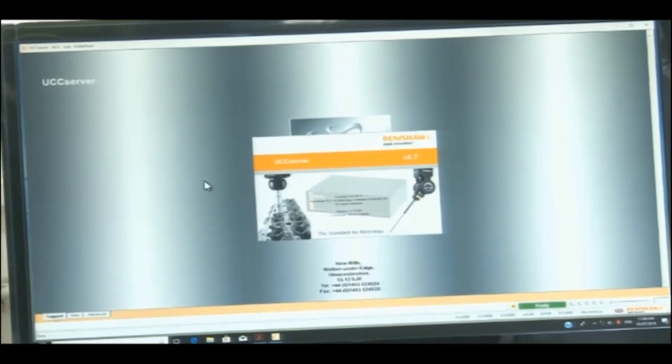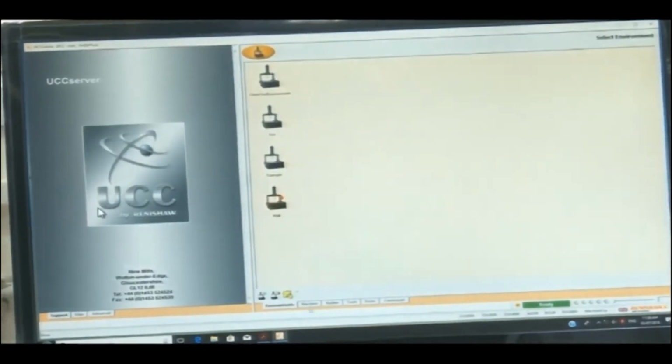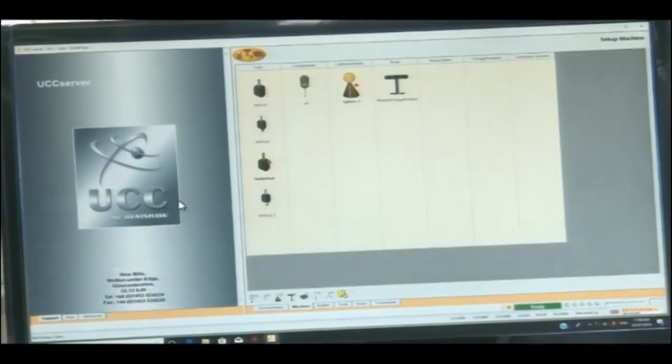So this is the host computer, and we have the hardware machine: read heads, probes, probe head controllers, limit switches, emergency stop, analog signals to servo amplifiers, joystick unit. All these things are the components of the coordinate measuring machine. The purpose of UCC is to permit the control of the CMM from the front end software. The controller provides the control signals to the CMM probe system necessary to give the required response, for example, to position the target to the given parameters.